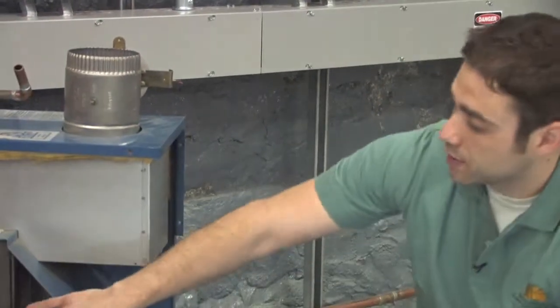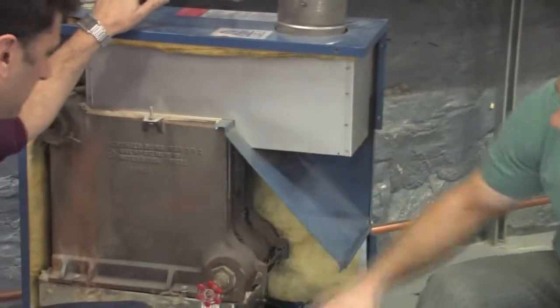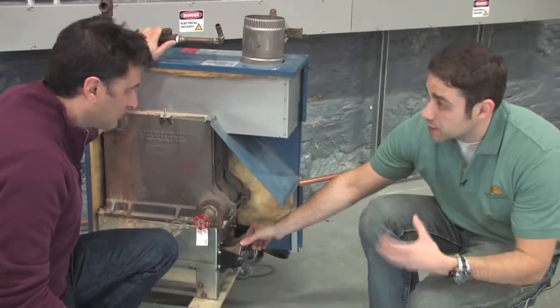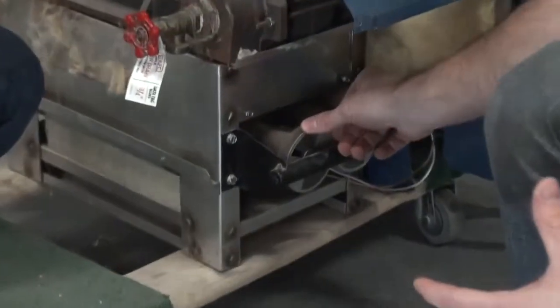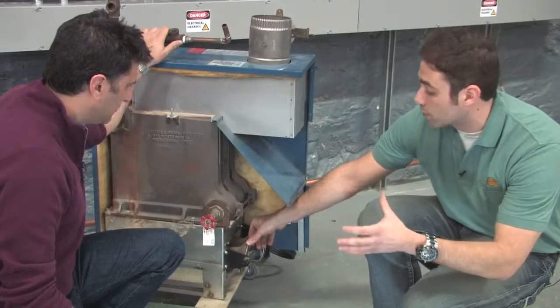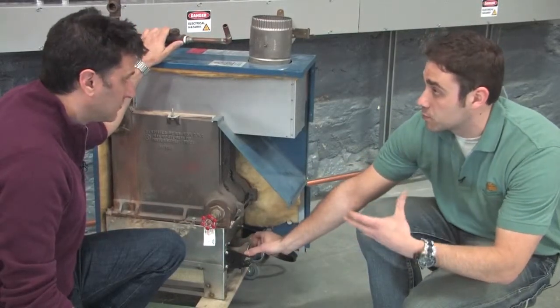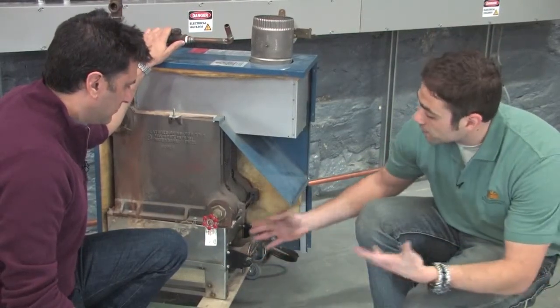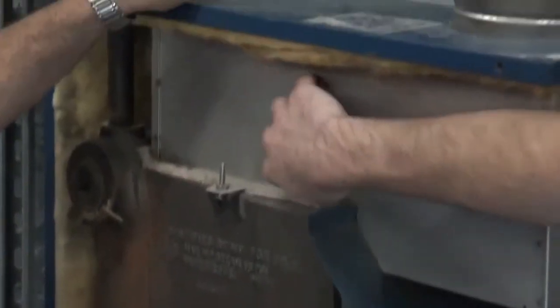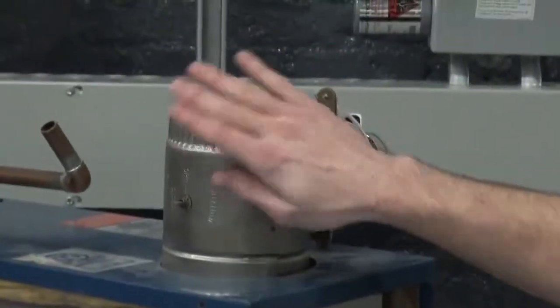So this heat exchanger, as you can see, is a real simple design. The burners are here on the bottom. These burners actually have a little air adjustment on them, so we can adjust the amount of air that goes into the combustion process. So if we do need to change the process and we have poor combustion, we can add or remove air with these primary air dampers. The flame burns, it goes straight up to the top, heats up this cast iron, it gets collected, and then it works its way out through the flue piping.